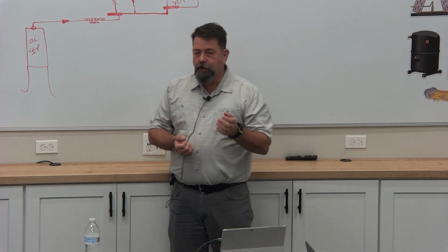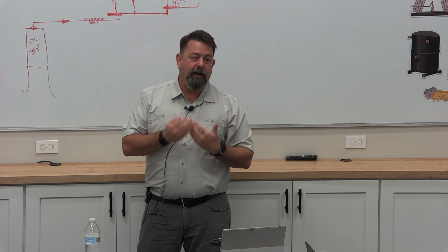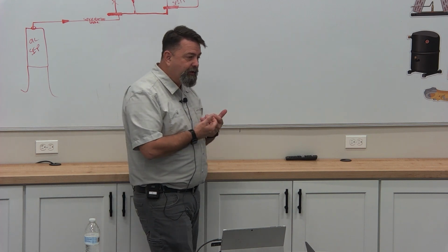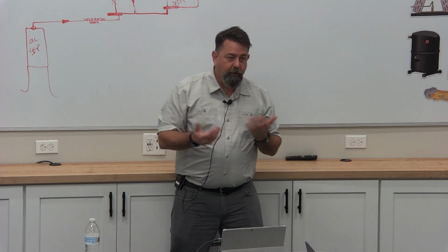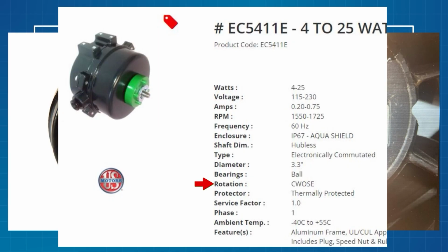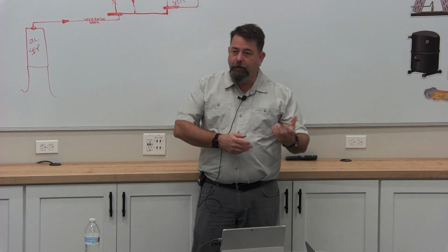So there's a bunch of different letters that you're going to start seeing now after CW or CCW, you know, counterclockwise. You're going to start seeing O, which means opposite. If you see the O, it means opposite. If I don't see the O, that means from whatever it's telling me. So this one is giving me shaft end, SE. That means it's always going to designate shaft end. If there's no O, that's from the shaft end. If I have an O, that means back. Great, shaft is not too bad.